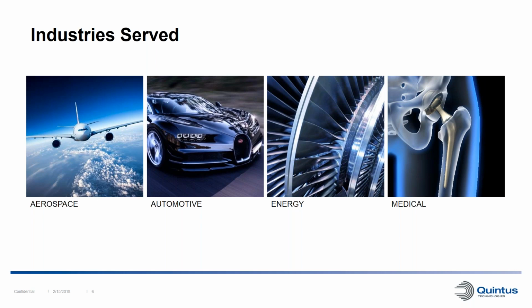In the oil and gas industry, as well as in the nuclear industry, powder technology is used to consolidate powder through near net shape for either a final part or for a billet. Medical implants is also an interesting sector for hot isostatic pressing, where typical parts are knee implants or shoulder implants and also hip implants. Something interesting to notice is that all of these sectors are very interesting for the fast-growing metal additive manufacturing sector, where hipping is crucial to achieve the material properties needed, as will be presented throughout this whole webinar series.